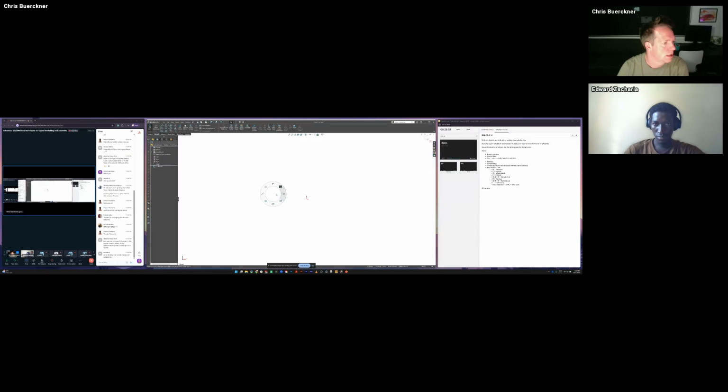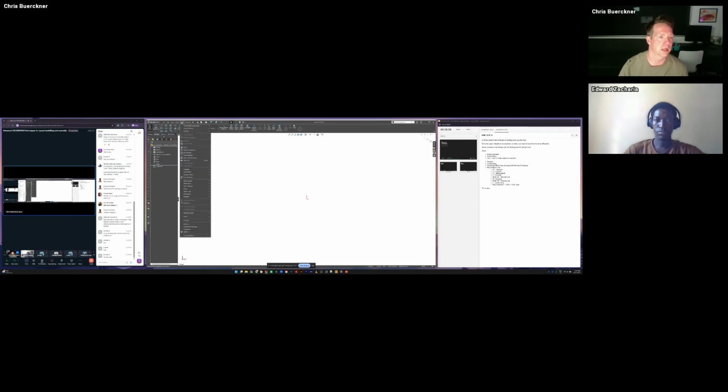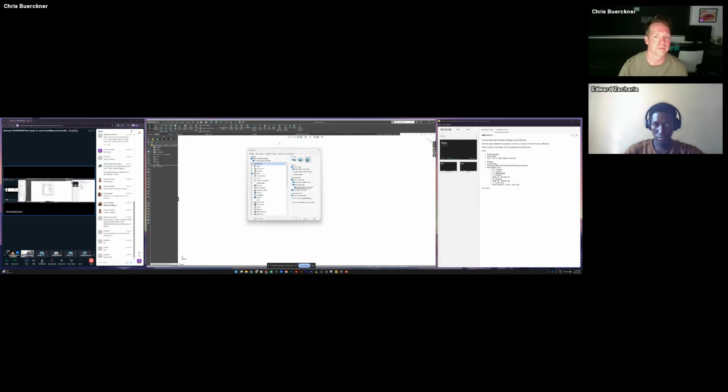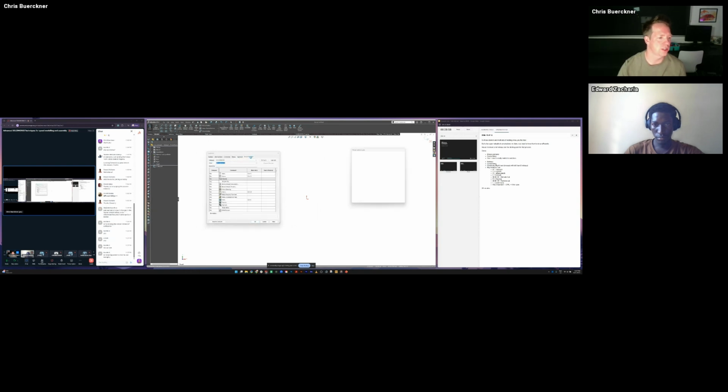Gesture, now you can see it. So this is where you right click with your mouse, and you can see gestures come up. Where I use gestures a lot is in sketching. To customize your mouse gestures, you want to go to anywhere that you can customize your options. That can be under Tools, Customize. This gives you customize options for your toolbars, shortcut bars, commands, menus, keyboard, and mouse gestures.